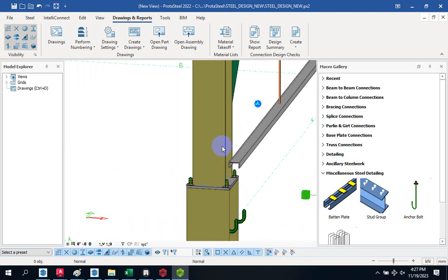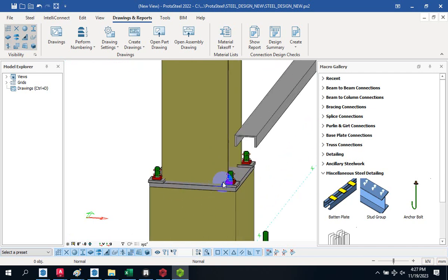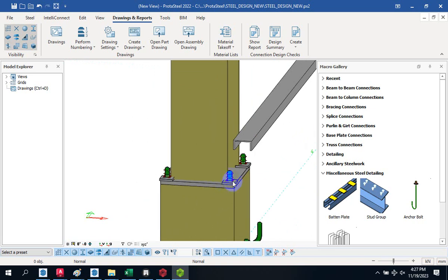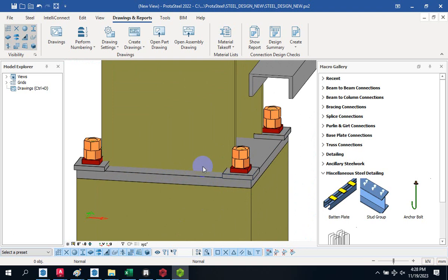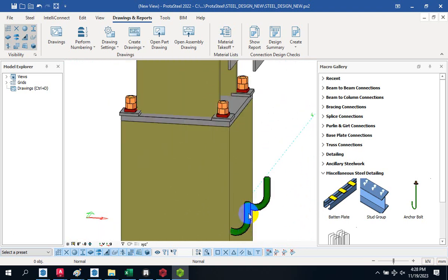What happened was this steel cross section is large, and the cross section the engineer is specifying for the column is 400 by 400. So you use your discretion. You as the engineer know that this concrete column you are supposed to make bigger so that you have better space. So the base plates will go round the concrete column, then you have reasonable space. Or you can reduce the anchor bolt to a smaller one if it passes. The main thing is for it to pass.